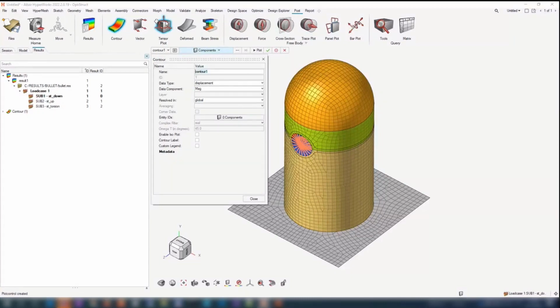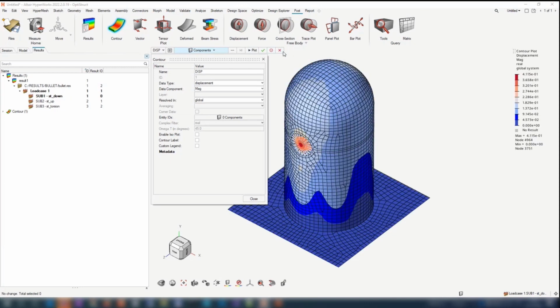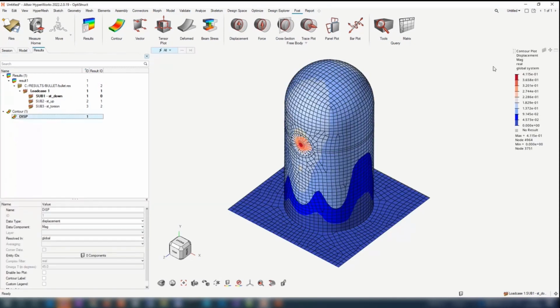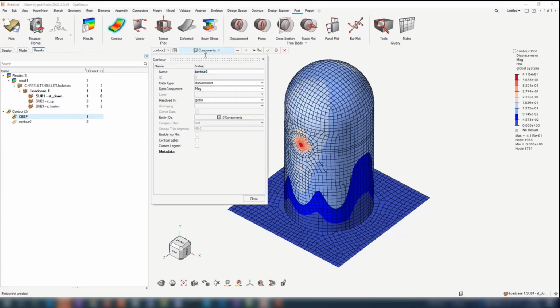Obviously, tensor wasn't there at all in the data structure of the REST file, but you can use contour and vector at your convenience, and you can use the standard plot control workflow to display anything that you need. You can add different types of plot controls, add your max principal. In this case, you can plot it.